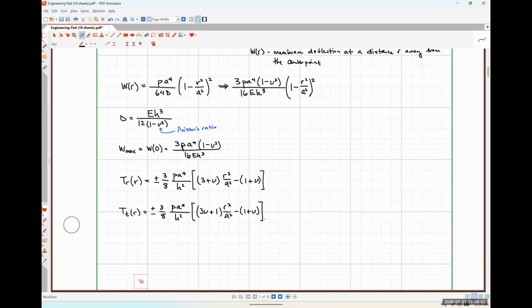We could think of it as breaking it down into little parts, a whole bunch of essentially guided beams where the region around the perimeter is the anchor of these individual beam parts as they're deflecting. So we should expect to see maximum stress at location A anywhere around our circular membrane.